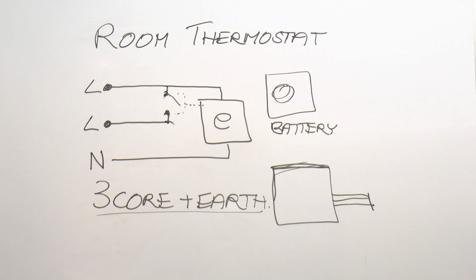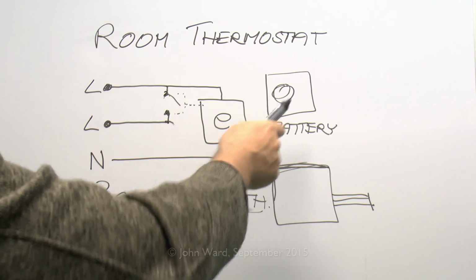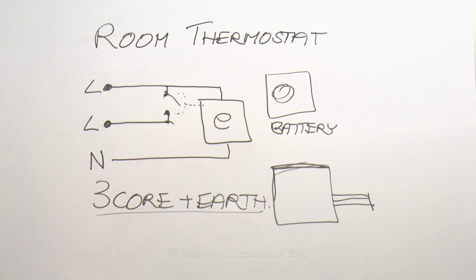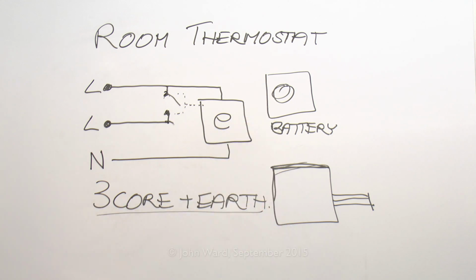The only benefit of these is that you don't have to put a cable from the actual controls or the boiler to the thermostat, so possibly maybe saving damaging the wallpaper or whatever. But in terms of connection, it's exactly the same. It's just that the connections are done at the remote receiver unit, not where the actual temperature sensing part is located. Of course, this type also costs considerably more than the permanently wired in variety.